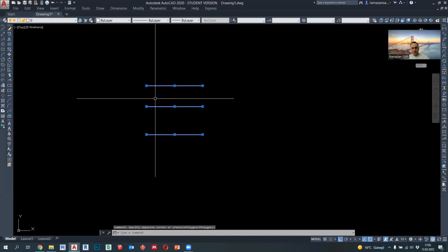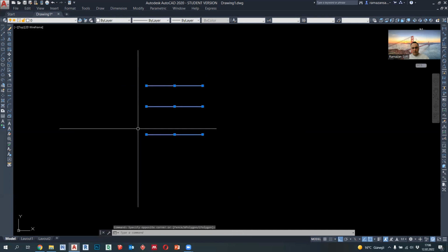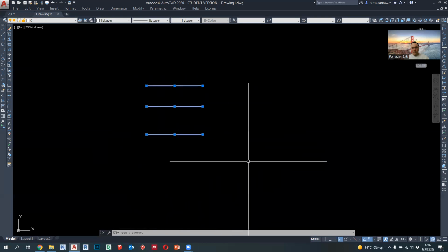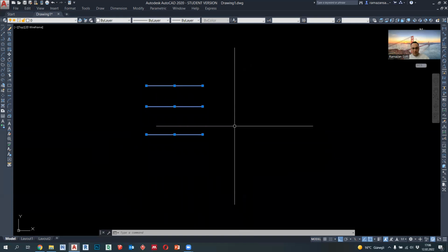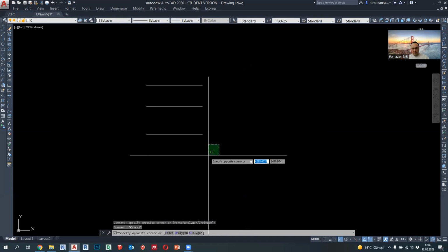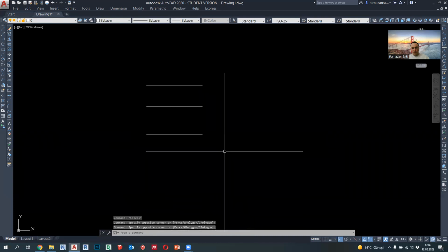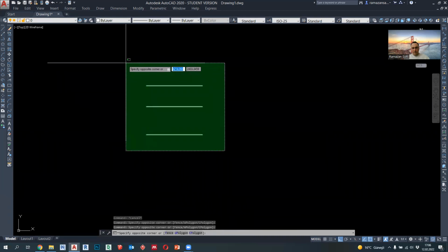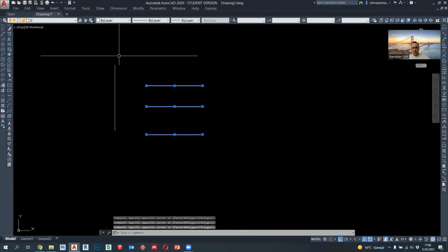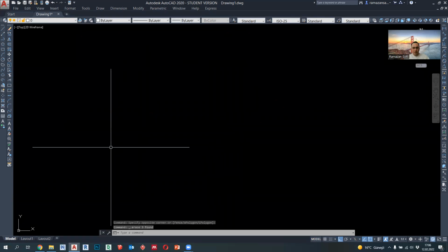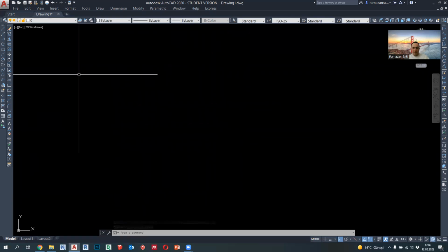You see the lines created and within the limit of the selection area are selected here. You can do the same thing from right below to left above. You see the same command, and again click delete button, and all the lines created will be erased.